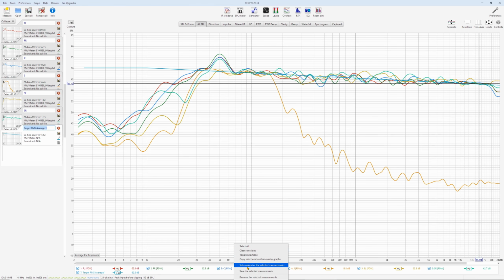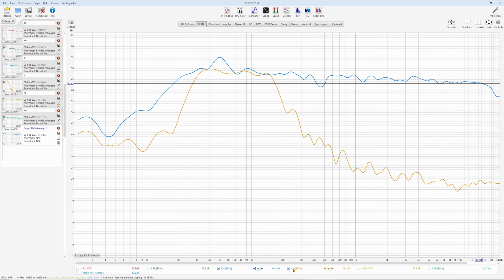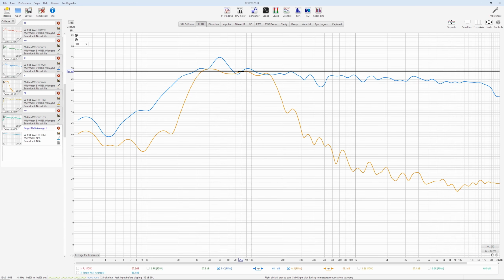So crossing them over, for example, like Audyssey does, let's say this is center and this is subwoofer, and Audyssey checks for the crossing points and probably will do this at 80 if it gets it right, because there's an intersection here. This is too low and this is too high. That's what it's gonna do. In fact, it should leave this speaker as large because its bass response is better than the subwoofer, but this is not gonna be the case with you.